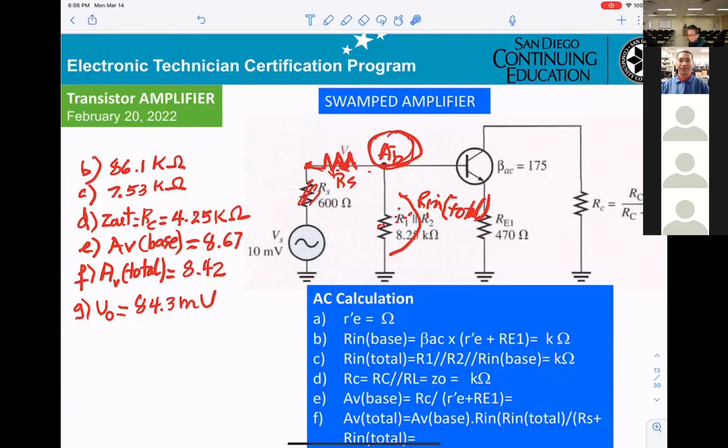You're not talking about 50 ohm here. On this generator, they gave you 600 ohm output impedance, not 50. So don't worry about any 50. Right, so in comparison to the safety resistor, how accurate would your AV be if that resistor started to go out of tolerance?